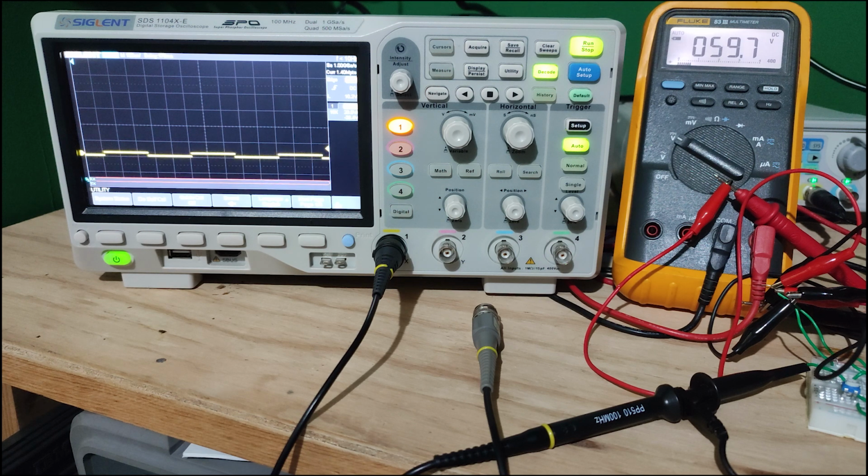It shouldn't be like this. It should be close to the power supply, let's say, but it is not working properly. So we have damaged the OPAMP. We have gone back to the safe value, which is 32 volts, and the OPAMP is not working properly anymore, so we have damaged the OPAMP. So don't increase the supply more than it is indicated.